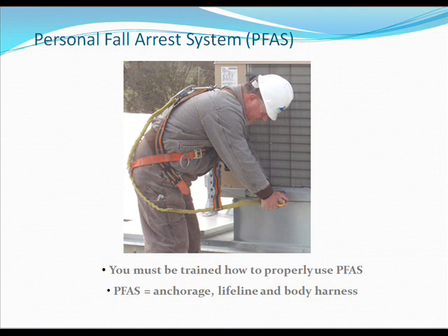Here are a few key requirements. There should be no fall from more than 6 feet. There should be prompt rescue after a fall. PFASs must be inspected prior to each use. PFASs must not be used until they have been inspected by a competent person.